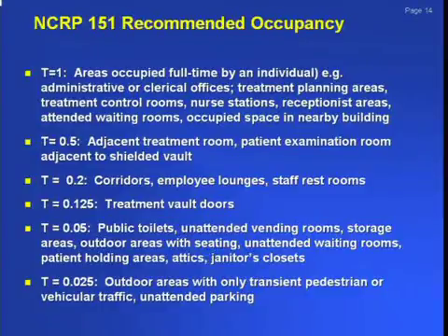Treatment vault doors, the occupancy is assumed to be 0.125. And again, be very careful with that because there may be an area that's closer to it with a higher occupancy. But that is the recommended number that you actually use for your treatment vault doors. Public toilets are assumed to be occupied no more than 0.05.